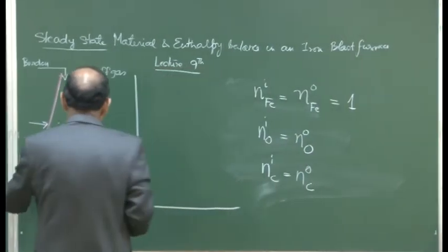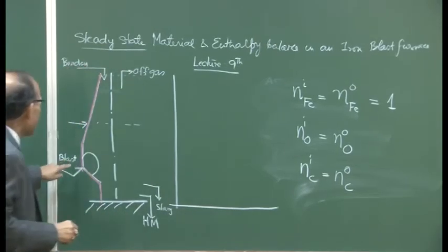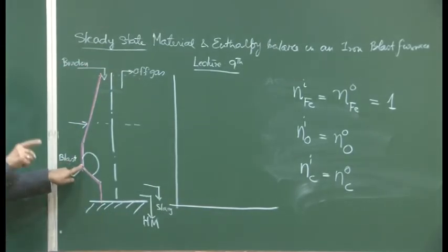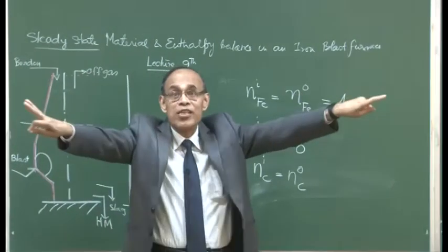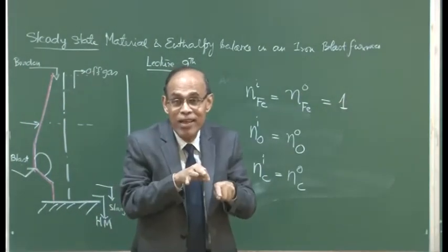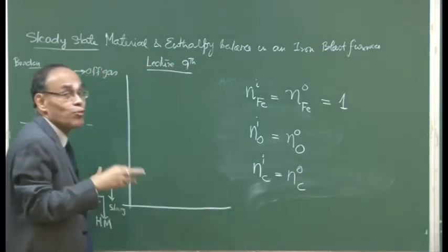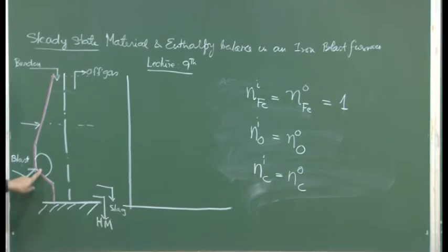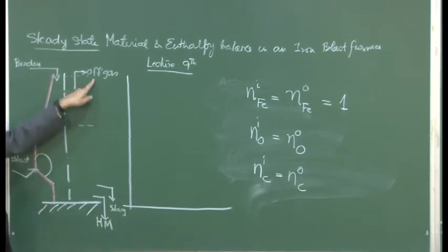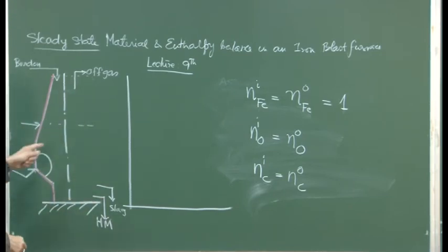So, the blast and top gas composition as well, how much oxygen I have to put in, because these are endothermic reactions. The moment you have to break iron and oxygen, you will have to supply heat, and that heat will come from combustion. So, you have to charge coke also into this ideal furnace. How much coke is to be charged? How much gas is going to be generated? What should be the off gas composition? Okay, and what should be the blast rate? These are the three parameters that we need to answer.